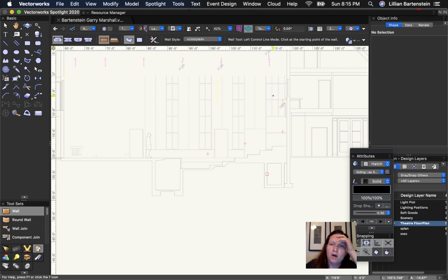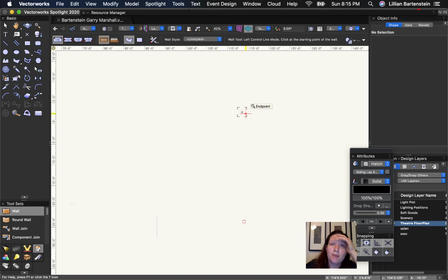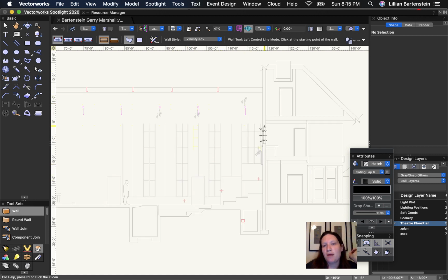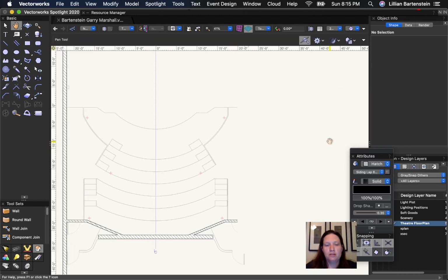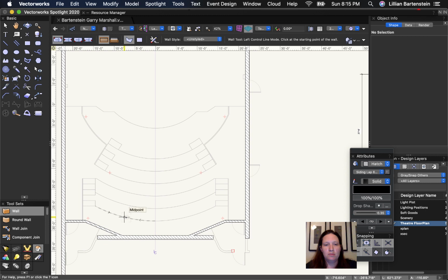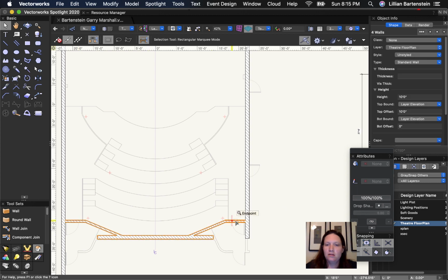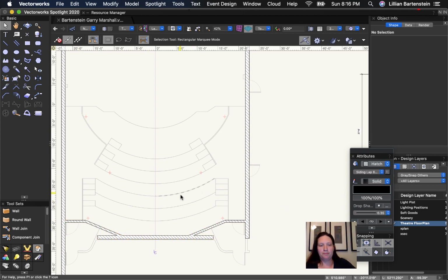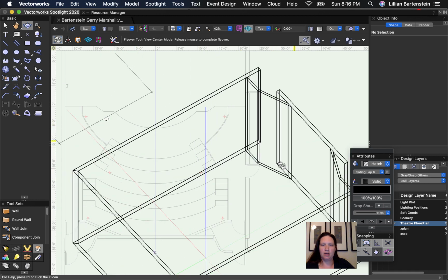Okay, so I'm gonna continue, it's gonna have the same overall height, so I'm gonna just make those back walls the same height. We can talk about putting like a booth window in if you want later, but for now, I think we can be pretty secure with our choices about making all of these walls 27 foot 6 inches tall. So let me grab my X key and let's select these walls. All right, so now escape, shift C, now I have my walls of my theater space. That is a great start.